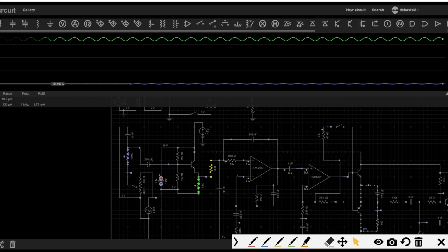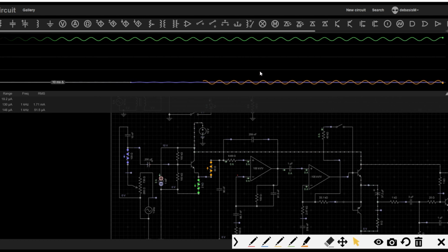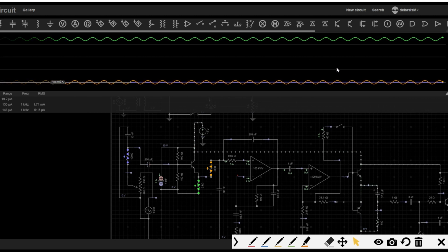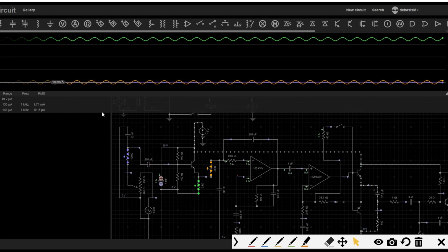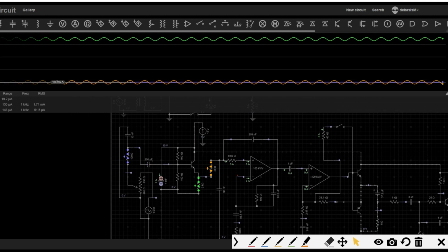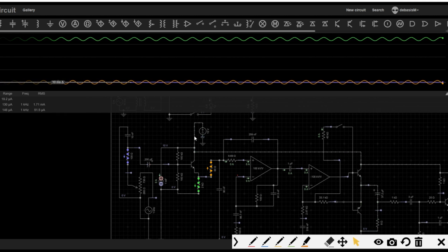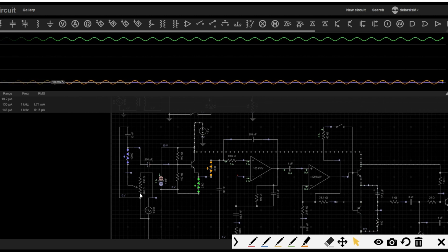Now how much current is the downstream circuit actually drawing? You see, the downstream circuit is not drawing that much current, that orange line, but the drawn current is relatively higher than the current supplied by the audio pin. It was around 9.62 microamp from the audio pin, and the circuit is drawing somewhere around 72.9 microampere. So in this specific case it's drawing somewhere around 8 times. That extra current is getting supplied by the actual power supply, not the audio pin. So that prevents the audio distortion. That's the key role of this section.